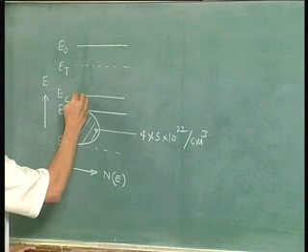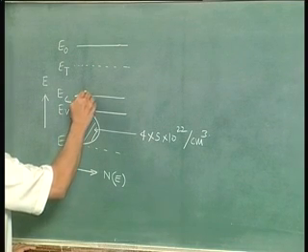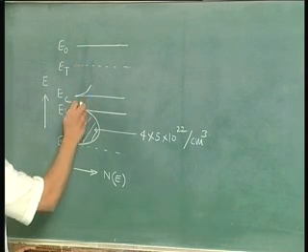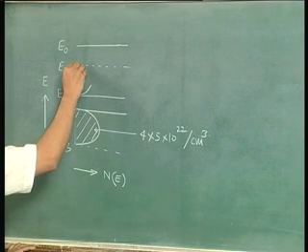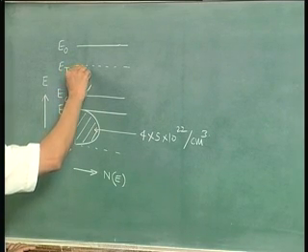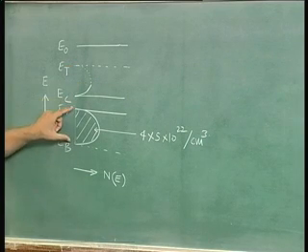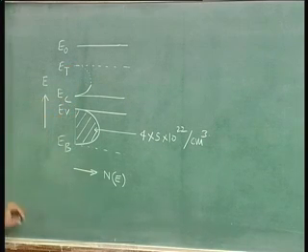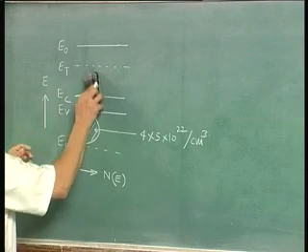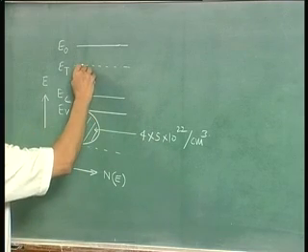You similarly have a density of states function for the conduction band, which we plotted only near the band edge, because we said that the shape of the function is somewhat more complicated than the density of states function in the valence band. So that is why this portion is shown by a dotted line.